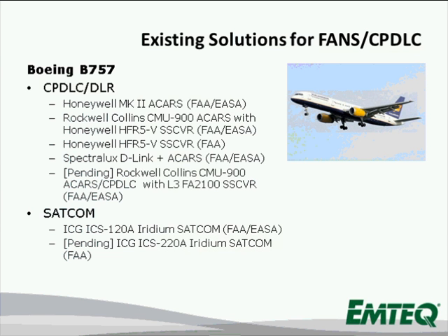We're also showing some of the SATCOM systems. Typically for FANS upgrades, a lot of operators, if they don't already have an Inmarsat system installed that they're wanting to upgrade, we can use Iridium SATCOM systems. And we hold STCs for those Iridium SATCOM systems that are typically provided by Boeing in a service bulletin, and they essentially parallel the installations that Boeing provides in their service bulletin at a little bit lower cost and quite a bit shorter lead time.